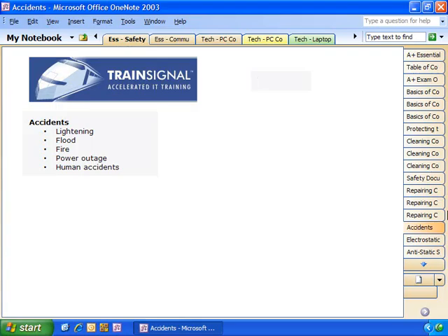The next one is a power outage. You can have a power outage completely, or you can have what they call a brownout, which is a low power voltage. You can even have a high power voltage spike. So all these things are best prevented from damaging your electrical equipment with a UPS, an uninterruptible power supply. It's also a battery backup, so if the power goes out, it supplies power during the time the power's out, either a brownout or a blackout. And it's also a line monitor and a device that conditions the electrical signal so that it doesn't damage your sensitive computer equipment.